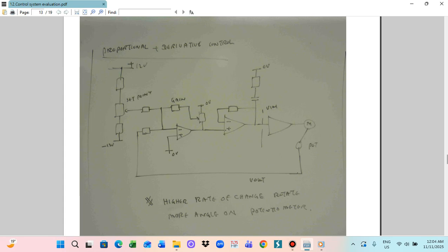Normally we use the transducer. The transducer is the converter. Here we use it for the controller. This controller includes the control systems. In this controller block module we include the closed loop speed control, proportional, integrated, and derivative control. Those modules are inside. Normally this controller can be utilized for the analog to digital to analog system. Normally the input signal is analog, so we use the ADC, analog to digital conversion. Before this lesson I already gave you the signal conversion, analog digital analog conversion step. In those systems we change to a digital signal, the control system operates, and then it changes back to the analog signal. So we use the ADC and DAC in the controller.